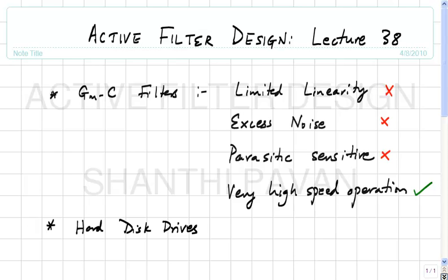Now if you attempt to pack more bits per unit area, it means that you cannot have magnetic domains which are all the way flipped one way and all the way flipped the opposite way for either a 1 or a 0. They will only be staggered very little, and from that you will have to figure out what the actual bit pattern written on the drive is. Okay.